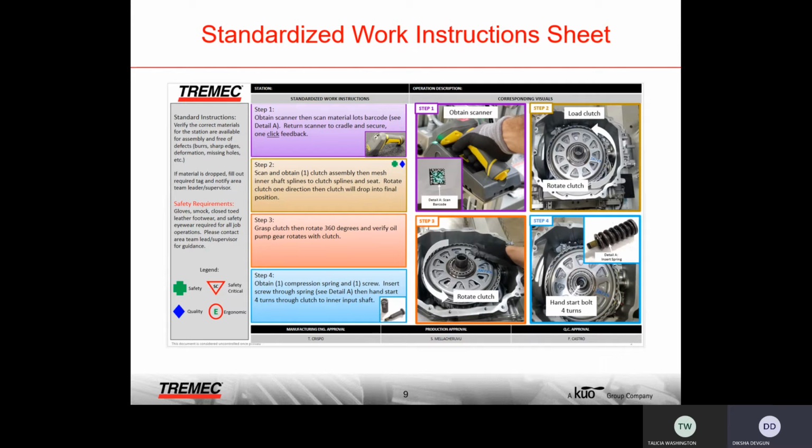Also, we wear a smock because we do not want any kind of debris or particle dropping inside a transmission. This is how strict our cleanliness requirements are for this transmission. We require all our people to tie up their hair, or put a hat on if you have shorter hair, because this can cause a huge failure at our end-of-line test, which we have seen a lot of.